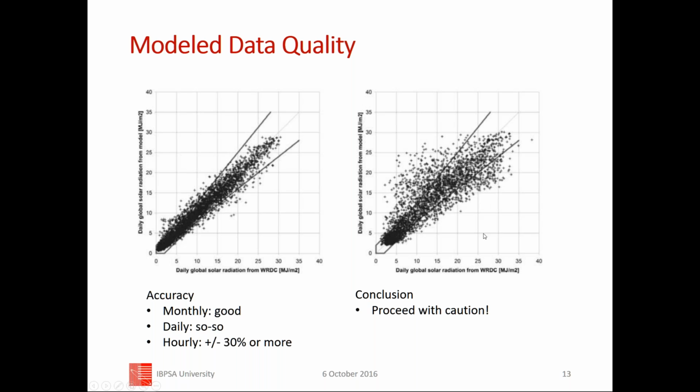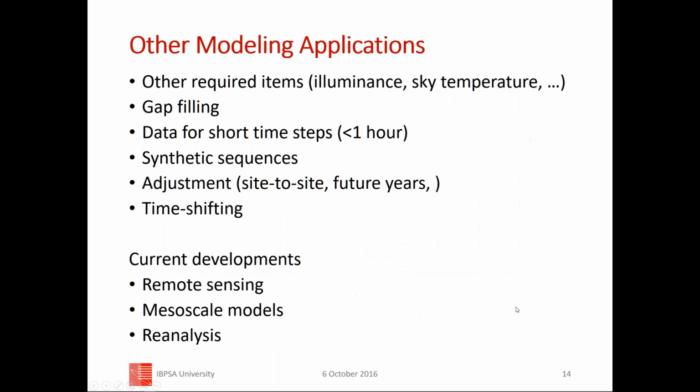And so the lesson here is that if you want to do glare analysis of changing lighting levels on a short-term basis using modeled solar or luminance data, you better watch your step. This is good enough, and in fact the best you can do for many situations for estimating energy consumption, but over a short-term basis, there's a lot of uncertainty in the individual values.